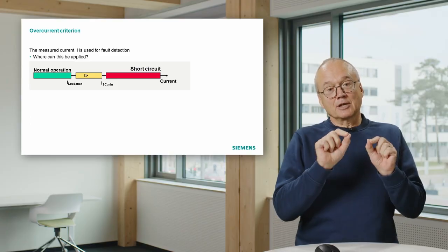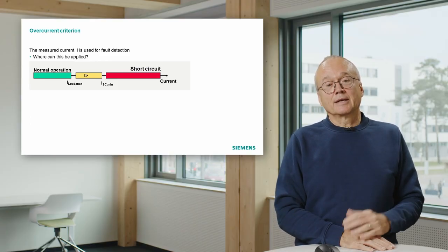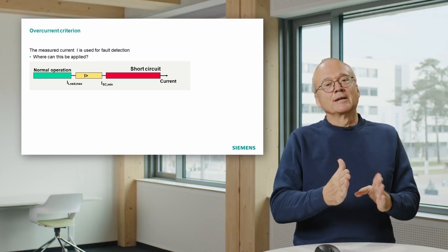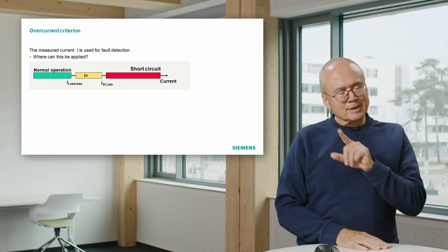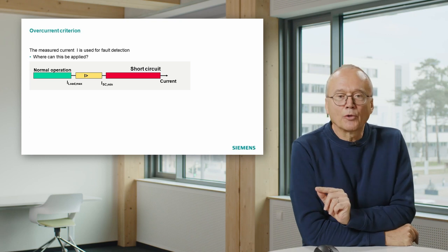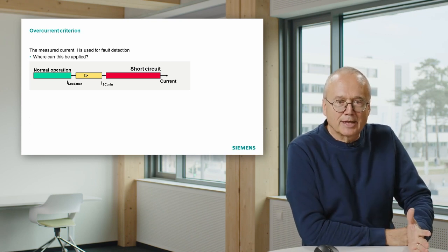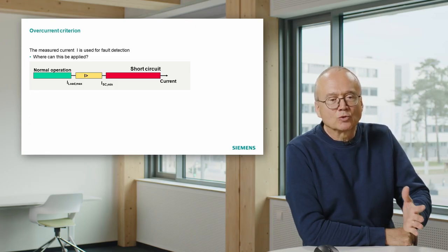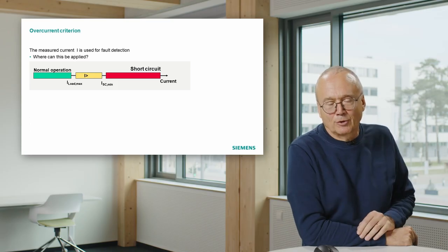And that means if you think about the maximum load current, you must take into account such considerations and must add a certain security margin there that you don't get this problem. The other thing you also have to take into account there is you have to look into the future, because you calculate your setting when you install the device, but you don't want to reconsider the setting every month.